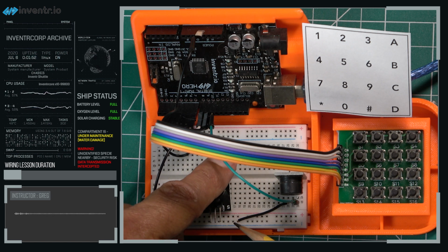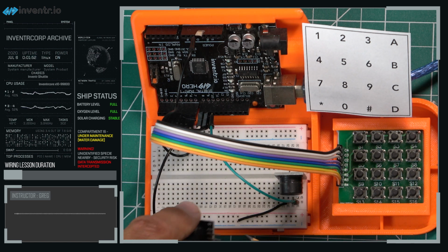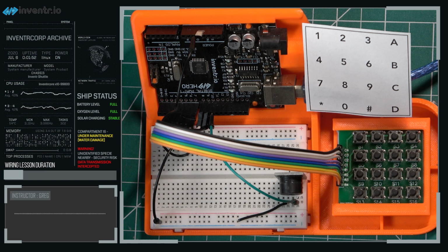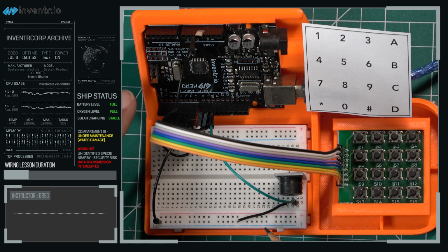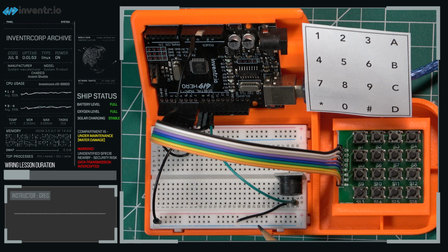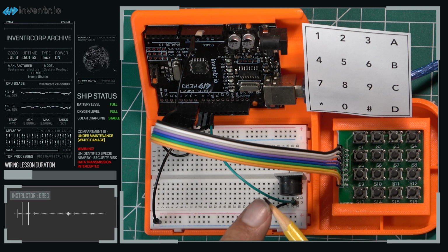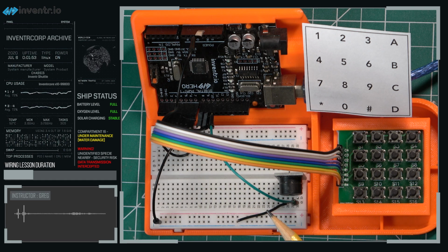And these will be the connections that we make to our hero in order to make the buzzer produce sound. If we turn our attention to the breadboard, we see that the buzzer's negative connection here on the left is connected to hero ground by way of this handy ground bus that we've set up by way of this black jumper wire. The positive lead, that is the S lead of the buzzer, is connected through this jumper wire to one of the hero's pulse width modulated output pins.